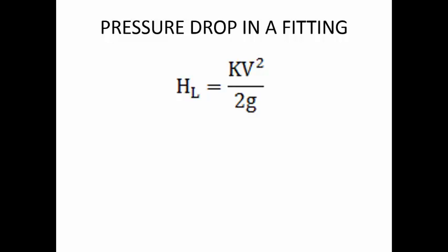So in order to standardize and simplify the calculation of the losses that can happen, we have something called the equivalent length technique. In this one, what we are doing is, you have a half-inch valve, which means the connector will also have a half-inch pipe. Now the loss will be specified in terms of the equivalent length. For example, we assume a half-inch valve will create a pressure drop of, say, 1 bar.